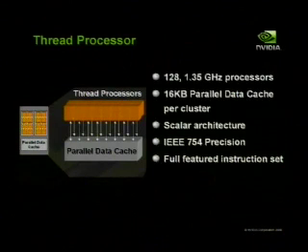On the last slide, was it 900 megahertz pin bandwidth, or was that the clock rate for the DDRs? That's the clock rate for the DDR. Okay, so it's twice that. No, it's divided by 2. This is taking the DDR times 2 number. If I look at the clock, DDR both edges, is that the data rate or the control rate? The data rate is, we see an observed 60 gigabytes a second of bandwidth. So each thread processor has 16K; there's your number.